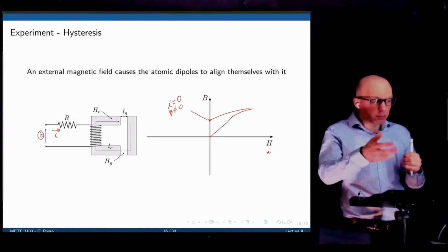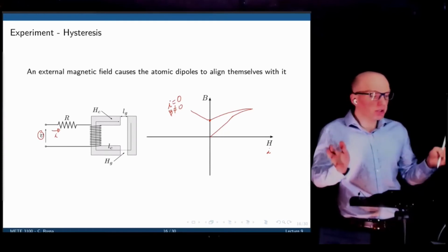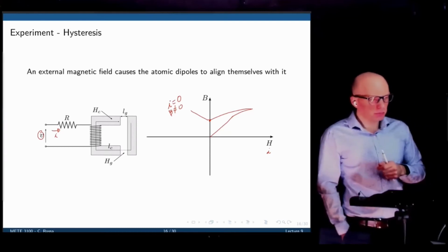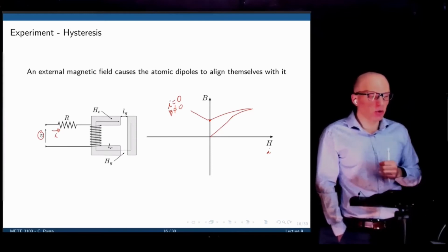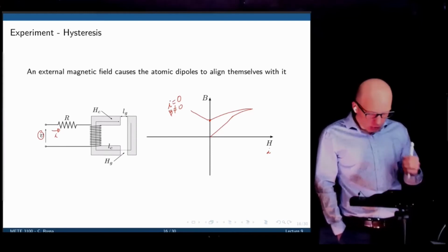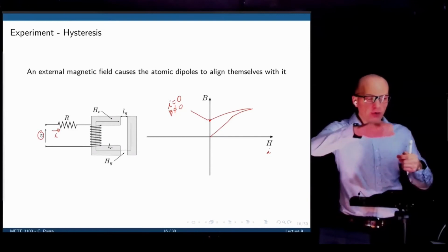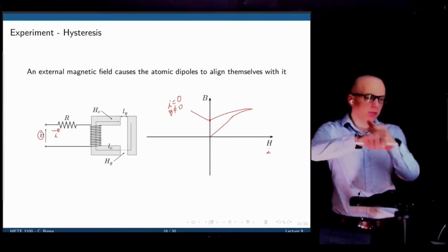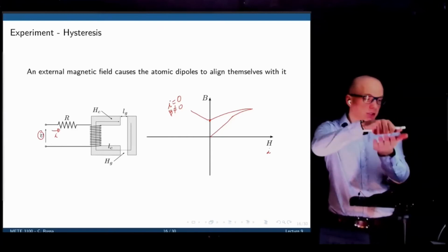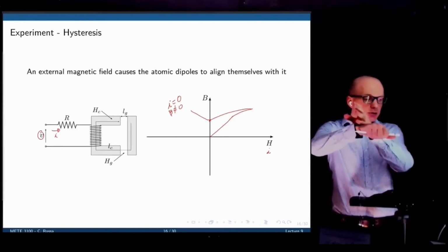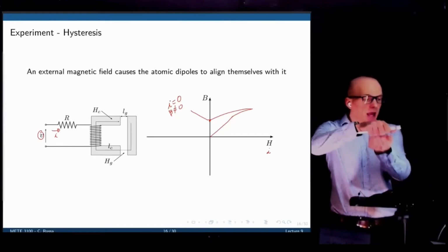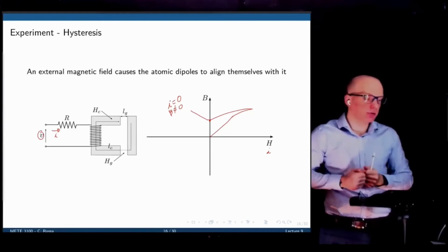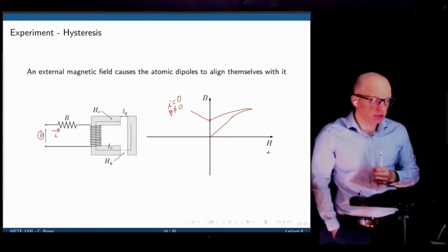The input power is zero now. There is no current being delivered, and yet there is a magnetic flux established in the core. So that's the effect of hysteresis, which means that in this plate here, if we take this magnet to lift something, we connect them, apply a current, so there's a force between them, and you turn off the current, the plate remains attached to the core, and it will take some force to let it go, to detach it. And this is due to the effect of hysteresis.